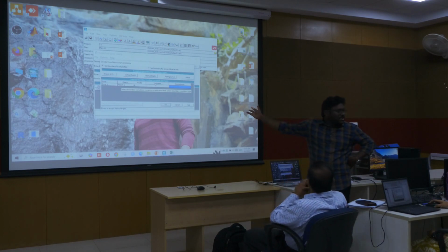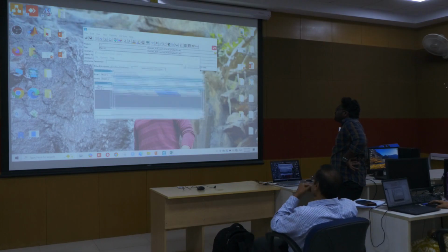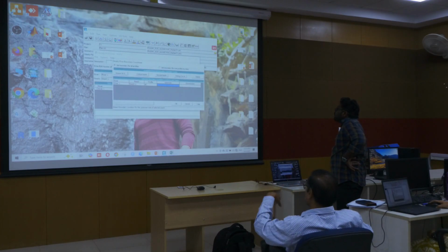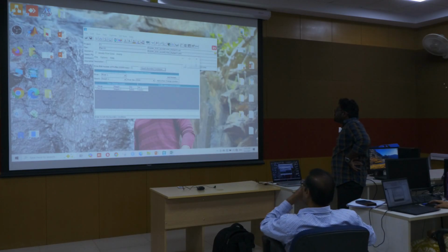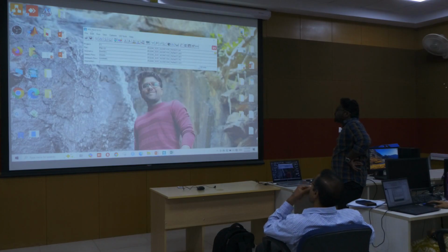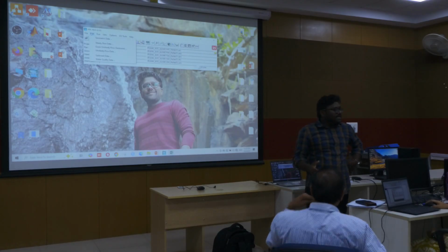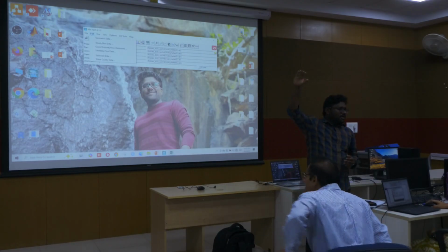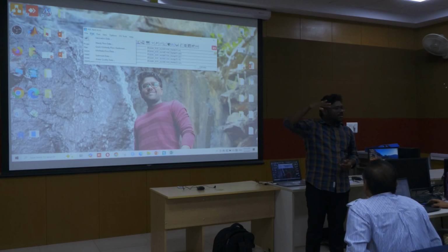Here we forgot to give the upstream and downstream conditions in the steady flow, right? So here you have to mention the upstream. Please repeat the steps. What I am telling is, if we have the peak flow, for example 20,000 meter cube per second, now see at that 20,000 meter cube per second, what is the inundation area?